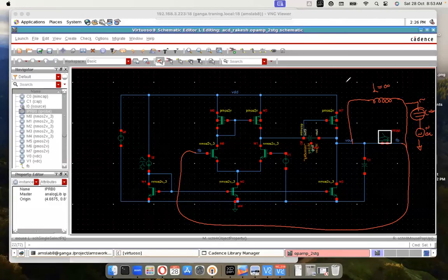Now what happens is, any AC simulation is nothing but DC plus frequency response. So initially it will do a DC simulation. When it does the DC simulation, all the DC operating points are set, and on top of which the frequency response is calculated. The DC is set as the inductor passes all the DC voltages. Post that, once the DC is done, now the frequency response starts.